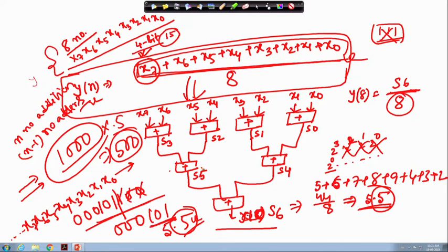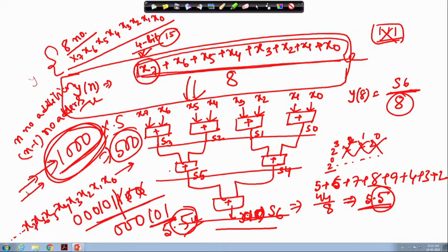So, this is the running average circuit, and this is the corresponding problem whenever we were doing it. Now, this is the corresponding parallel implementation, right. Now, for this, suppose what I said is that I have to do this 1000 number of addition operations. That means for the samples coming in this flow, I have to do the running average of these 1000 samples.